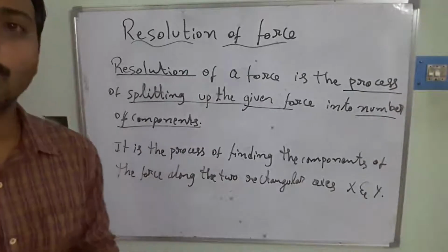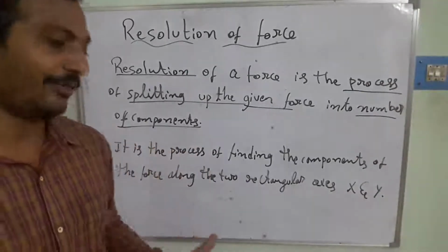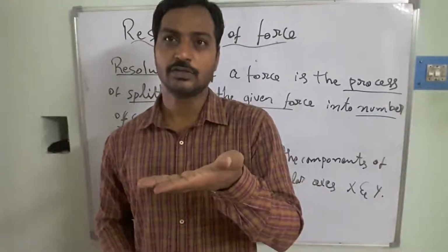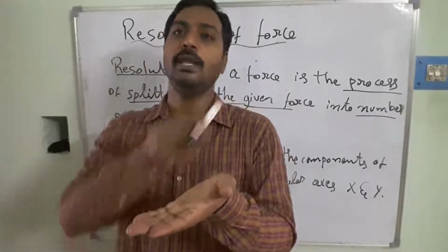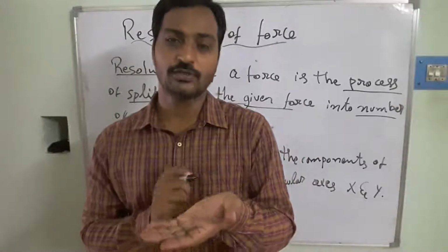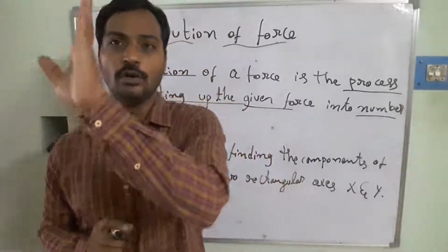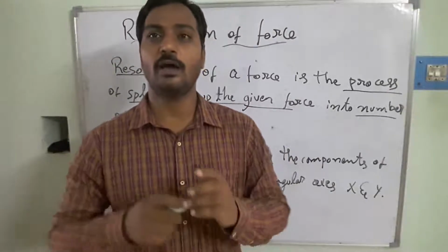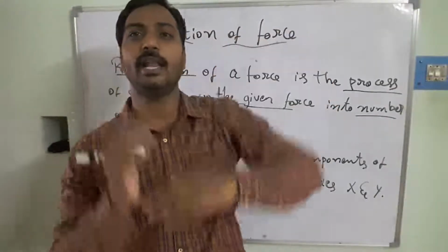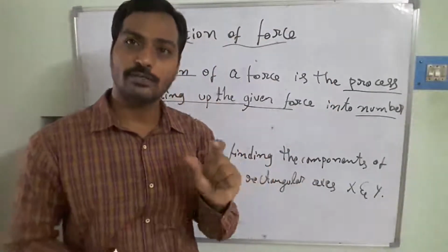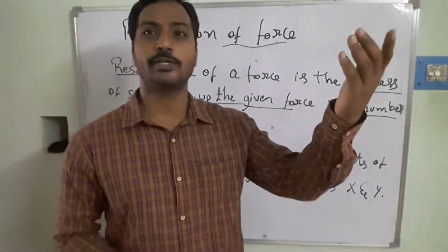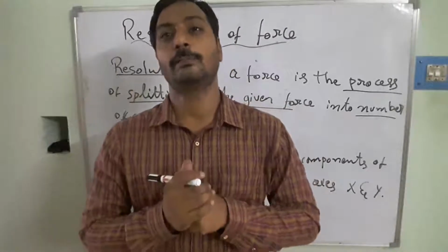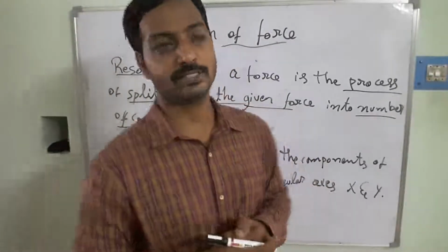In which direction? That depends on how we require it. Suppose a component is resting on a horizontal plane, then the force is inclined to the x and y axes, so we resolve the force into x and y components. Similarly, if the axis itself is inclined, and you want to know the force acting along the inclined plane and the force normal to that plane, we calculate it from this resolution.